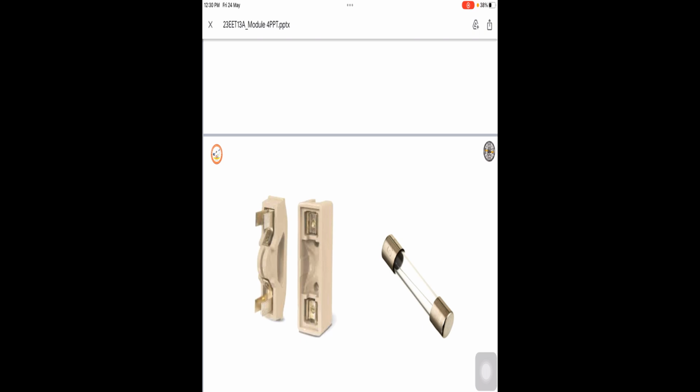A fuse doesn't require any maintenance. It is a very cheap application to protect your electrical equipment. It interrupts enormous short circuit currents without noise, flames, gas or smoke. It has a current limiting effect and negligible replacement cost. The fusing element cost, whatever we replace, when compared with the electrical equipment cost, is almost negligible. Easy removal for replacement without any danger of coming in contact with a live part.